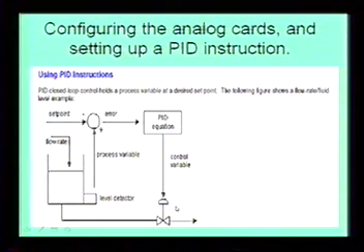So they're opening and closing the modulating valve, and they're putting this in terms of how RSLogix 5000 and 500 wants to see it. They want to see a process variable. This is the process variable, the feedback, your set point, your error. You can see here they went negative, positive, and you can actually reverse this relationship. Then coming out of here, you go to your PID equation, and coming out of that is your control variable, your CV, that actually modulates the valve.